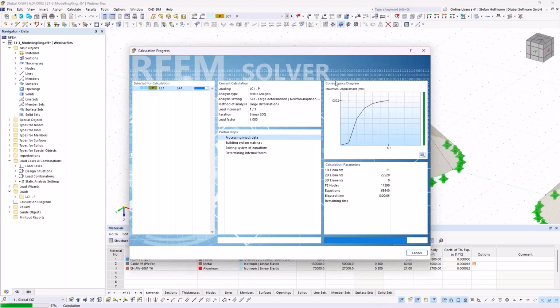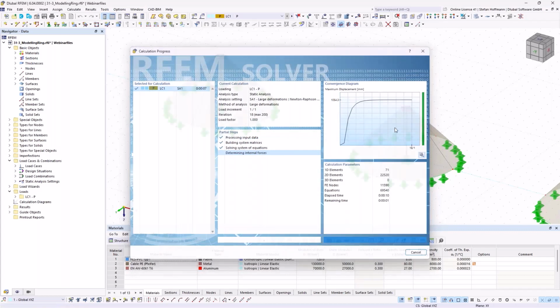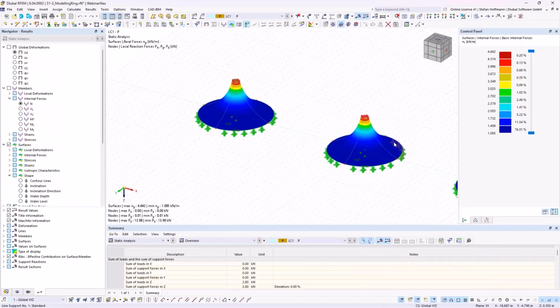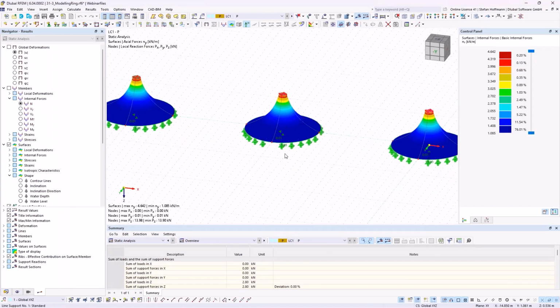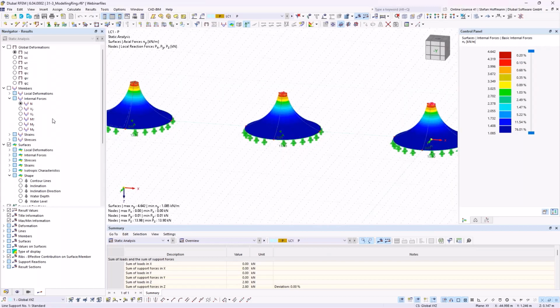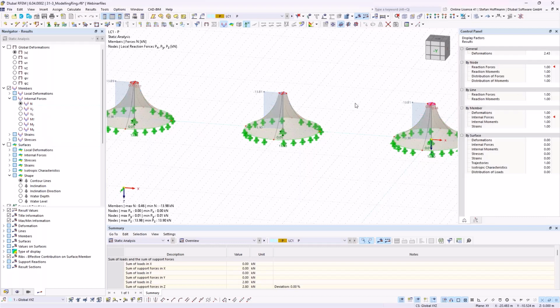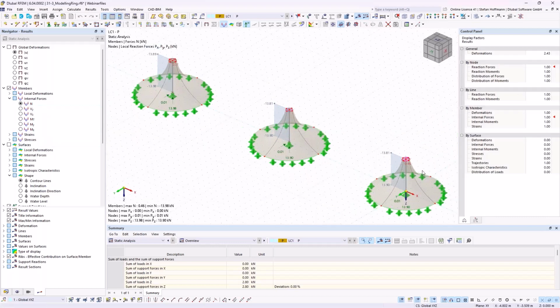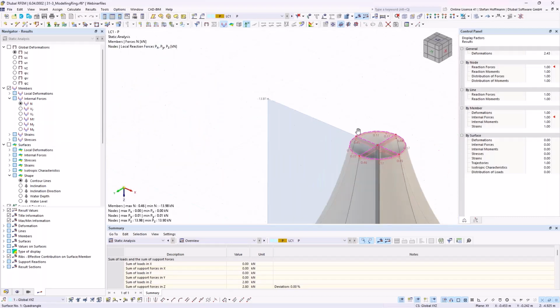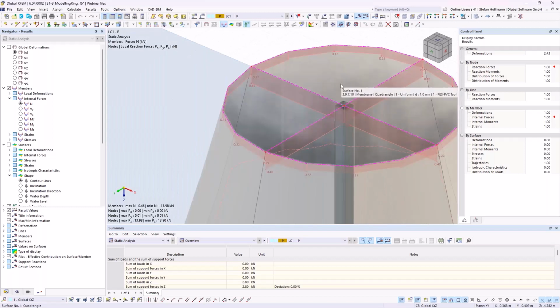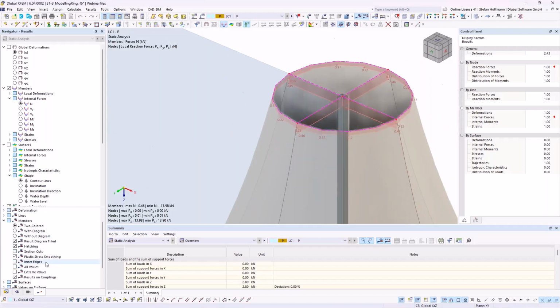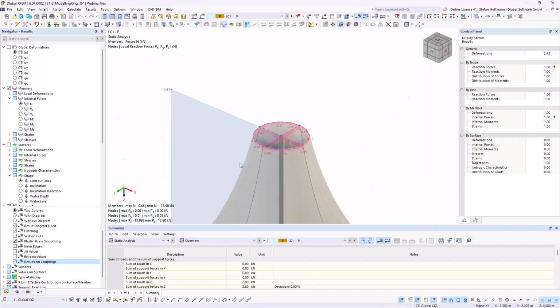Sometimes you need temporary supports, depending on the numerical stability of your file. For this, we don't need them. We can see that the deformation should be similar, and also the inner forces. But then the member forces can, of course, differ from our rigid connection over here. So we have here rigid members where you can, of course, also display the results on couplings.